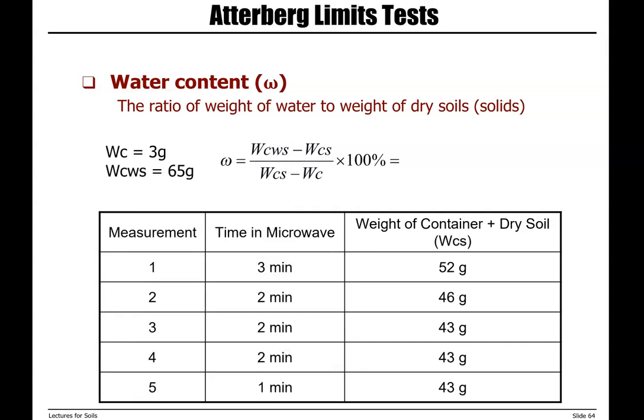So let's go over an example. We have, this is weight of empty container, 3 grams. Then we have weight of container plus wet soil, 65 grams. Then we put our soil sample with the container in a microwave and start drying.